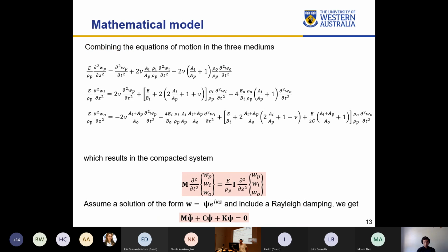All right. So if I summarize, we got three wave equations there that are important to take into account. The first one is for the tube. So if you ignore all the coupling terms, then you'll end up with the boring usual wave equation, if you want. But then these terms ensure that there is coupling between the inner and outer fluid. So the subscripts: P is for the pipe, I for inner fluid, O for outer fluid. And the same thing applies for the density, for the cross section, and so on and so forth, right? So that's the equation for the tube, if you want, with additional terms that are reflecting the coupling.